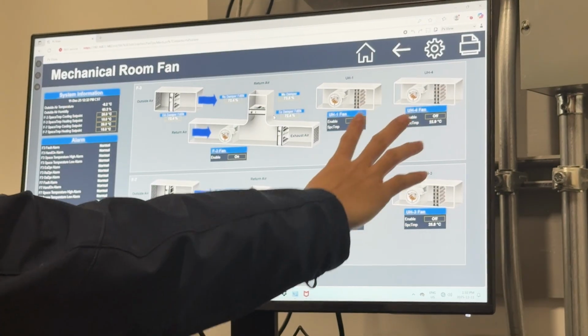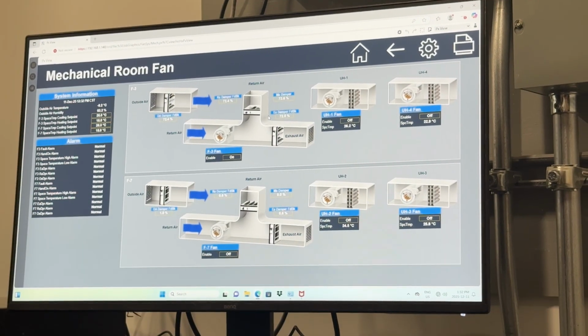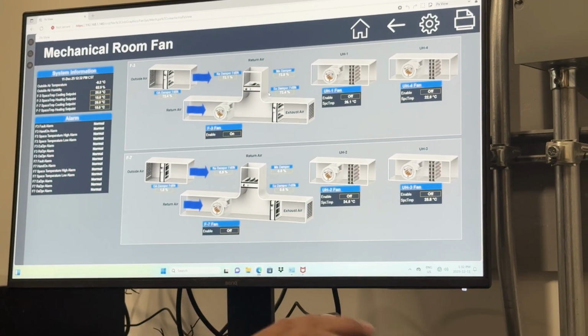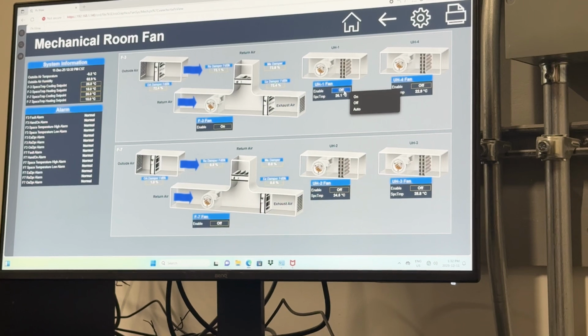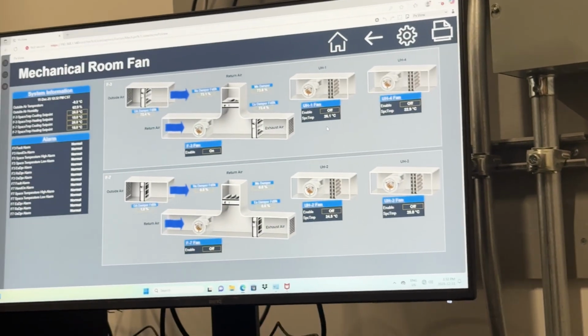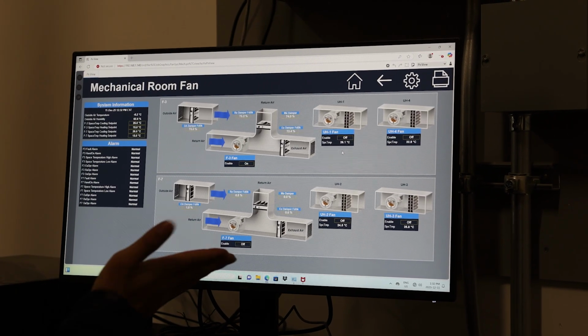So unit heater is for the heating, this is for the cooling. No. So BMS controls the unit heater for those 4 unit heaters. You can turn it off from the breaker or you can turn it off from the BMS as well. On the BMS, we can also turn it off. Because I noticed on the older building. I see. No, not for this system.